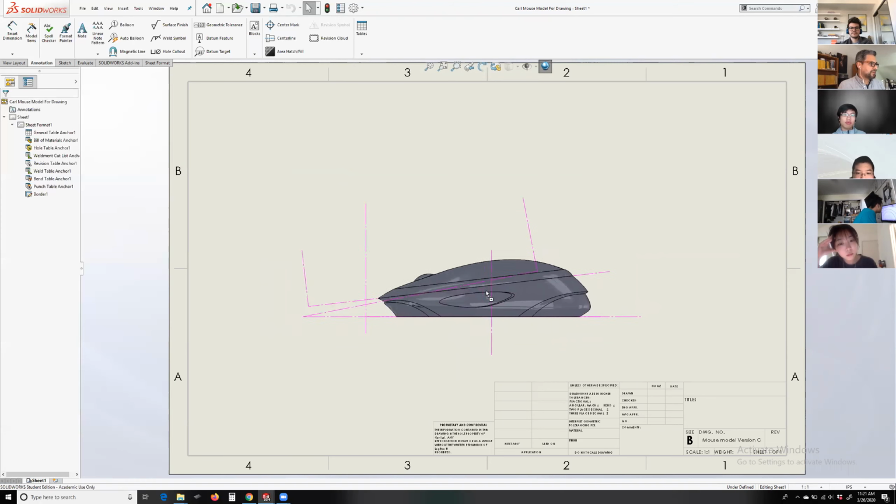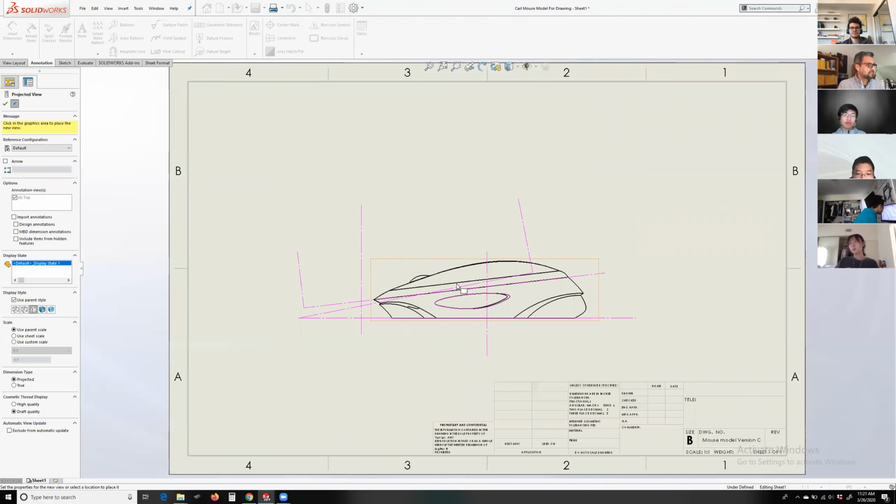When you drag this, I usually start off with a front view or a right view, something that's logical with the object that you're making. So I'll just click on this front view. Then automatically it's going to continue with the next aligned view. I'm not even dragging out, I'm just hovering over, see how it's projecting this rear view here, which is actually the right view.